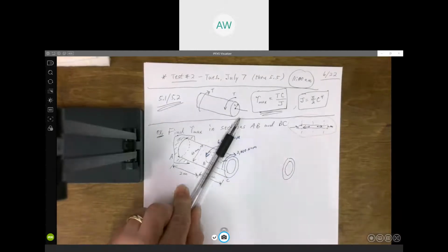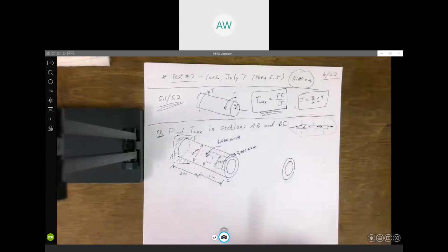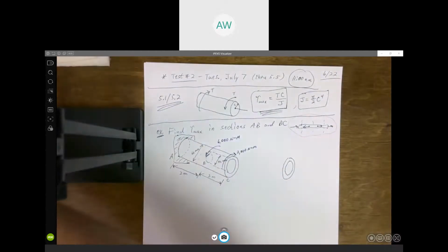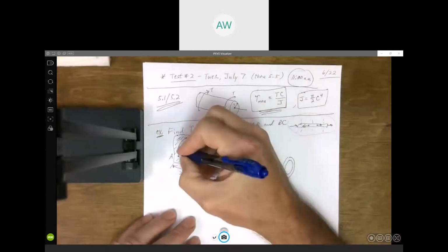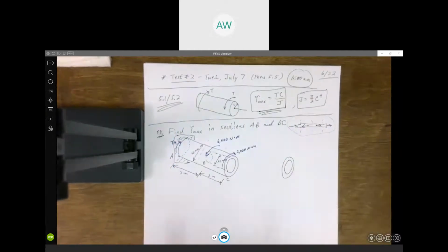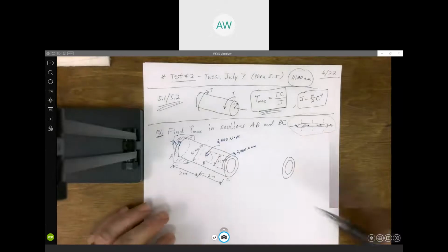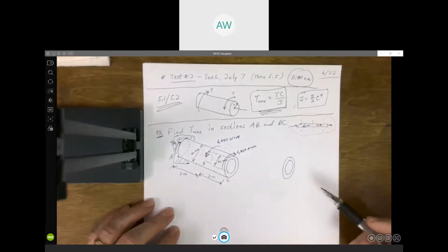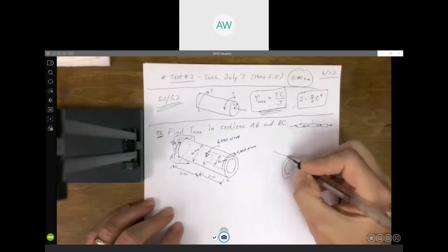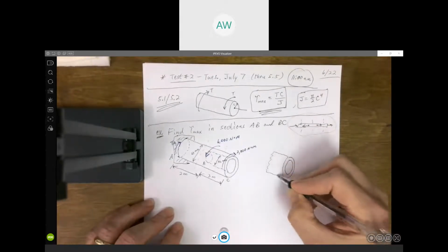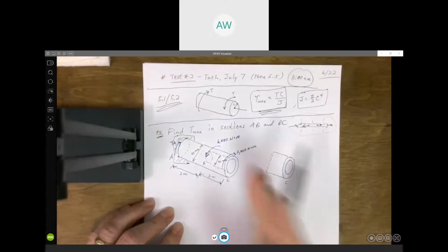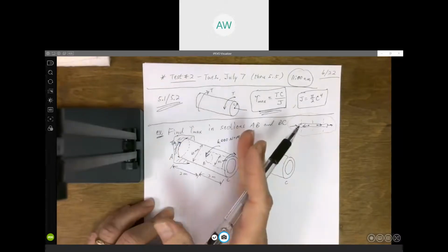Here, there's more work if we do the left side, because one, we would have to determine there's going to be some reaction torque here, right? The support reaction where this thing's fixed to the wall. There's going to be a reaction torque there. We'd have to calculate that. And there's more stuff over there, so it's less work to look at the right side here. So we cut this somewhere between B and C, and we draw everything to the right of that.